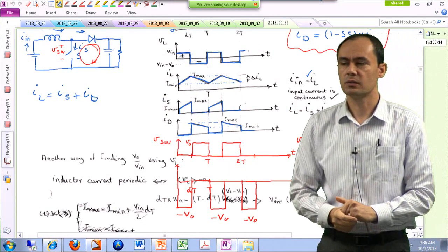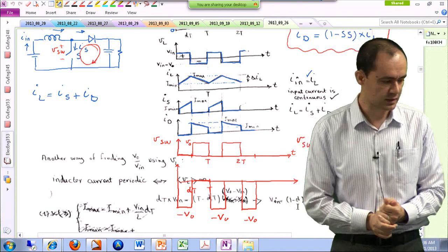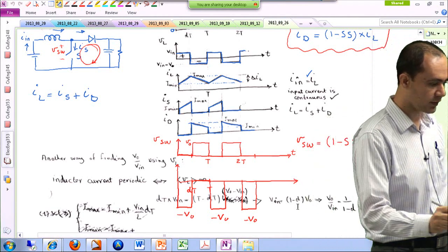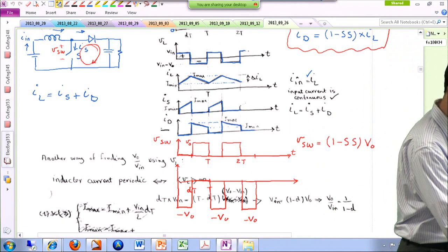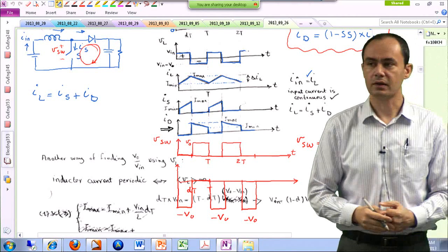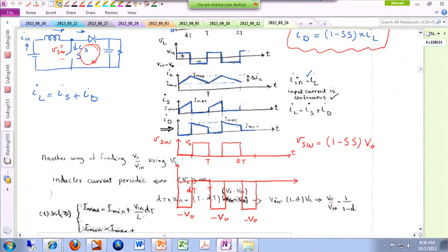We drew some of the important waveforms, and the waveform that we are going to start today with is this one: the current that passes through the diode. So if you look at the boost converter, the inductor, which has the continuous current, feeds the R and the C, the output side. Over here, we have the diode replacing the inductor. So we have to look at the current of this diode to be able to see, for instance, how much power is delivered to the load.